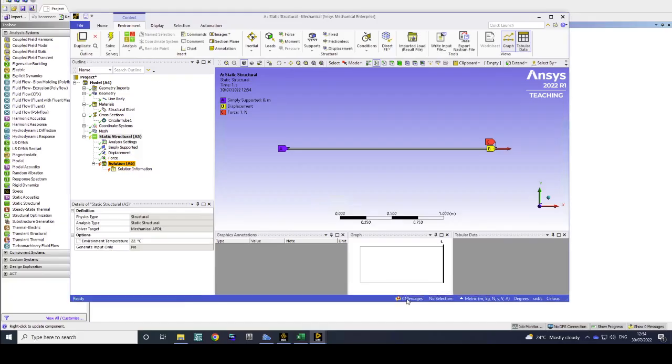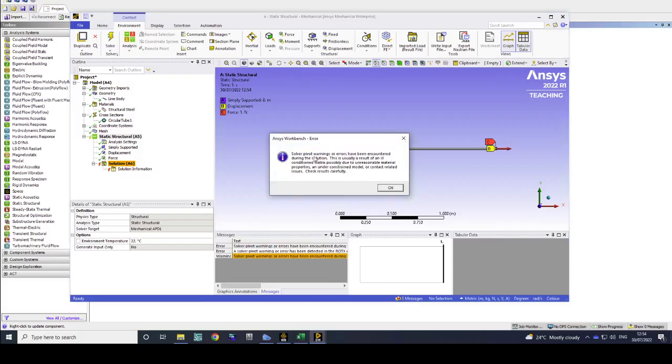The error is telling us that there is a pivot problem, and if you look at the reasons for that, this is what we call the singular stiffness matrix problem, or it's calling it a pivot warning or error. You can see one of the reasons is that we have an under-constrained model. And that is the reason that we've got this error here. So if you remember, I explained that not having adequate support can lead to this problem.